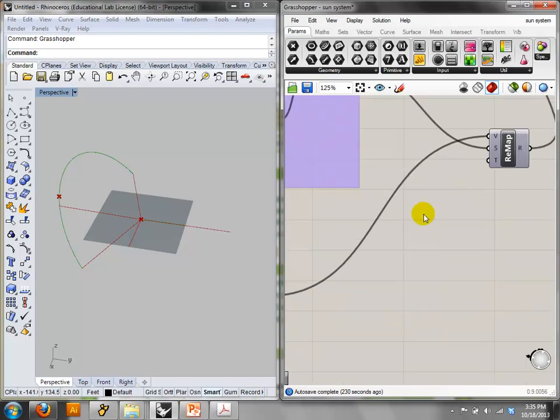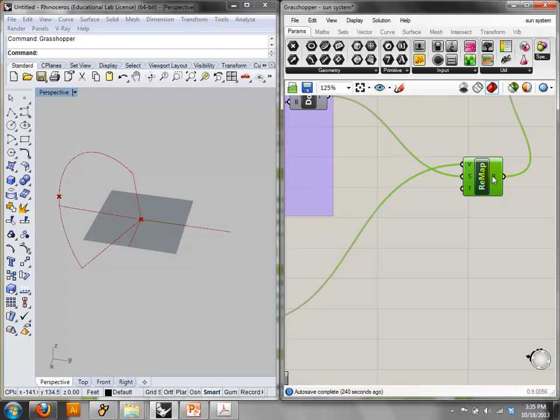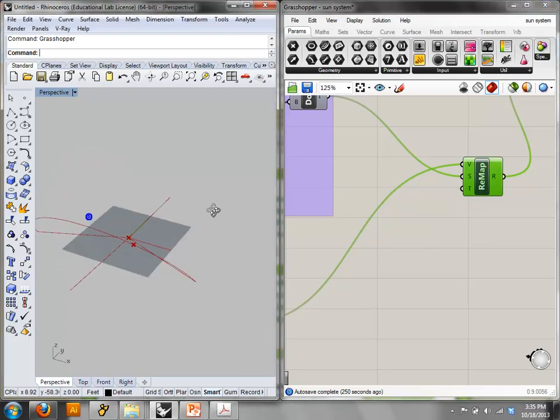This is 0, this is 1, in terms of our parameter. Then I figure out that 2:10 in the afternoon is 850 minutes after midnight, and I can use a tool like Remap to figure out that that's 0.69586 in the day. We're 69.5% through the day, and that is where the sun is.